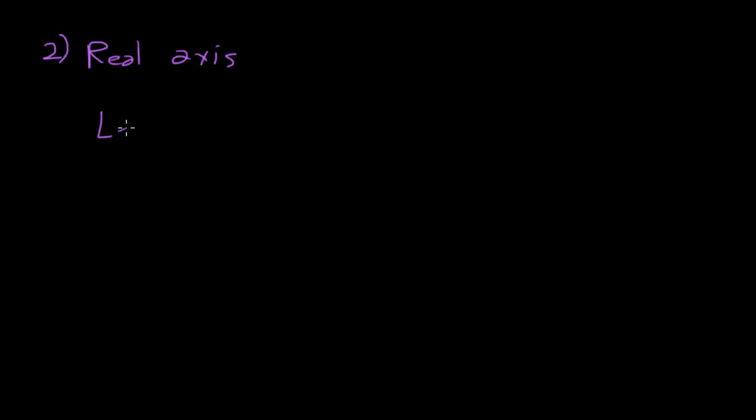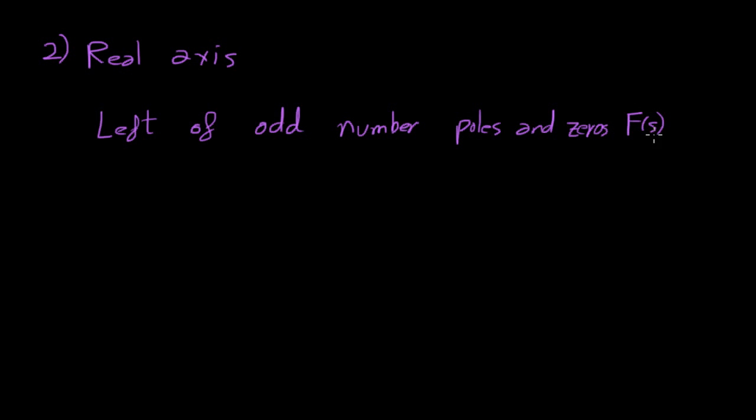Points which are to the left of an odd number of real poles and zeros of f of s belong to the positive root locus.